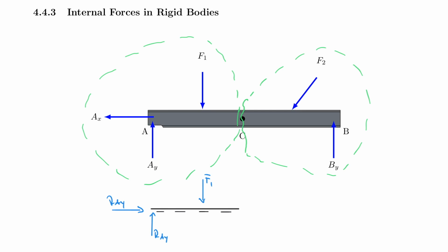And from now on you understand that I cut the system here, which is really at location C. So this is location C. And this system, of course, cannot be in balance because, yeah, maybe F1 is equal to RAY and then it would all be in vertical equilibrium. But again, you would have rotation, so it cannot be. And by the way, F1 here would not be equal to RAY unless it would be a very special case. And therefore, there's not even a vertical equilibrium.